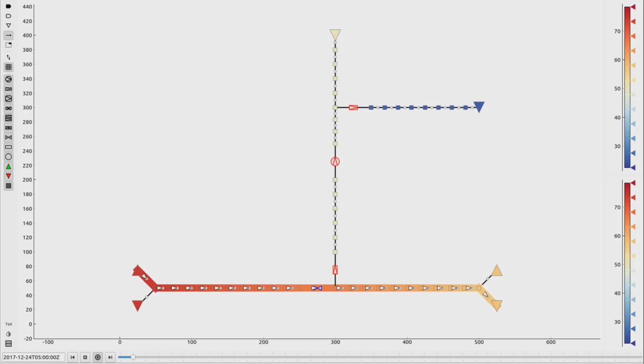Finally, you can also see the current state for each of the active elements. There are two different colors displaying the current mode. If the element is closed, then it has a red color. That means there's no flow going over the element and the pressure at its two nodes is completely independent of each other. For an active element with non-zero flow, the color of the element would be blue.